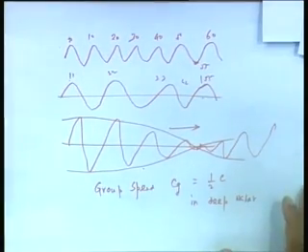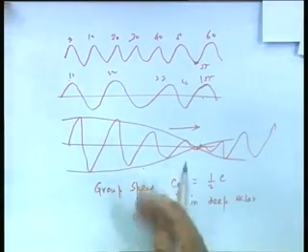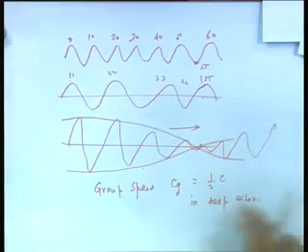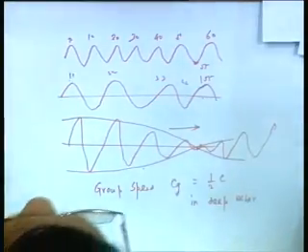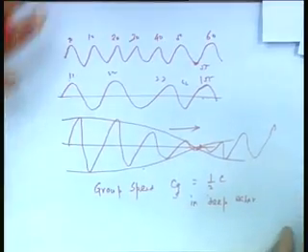In the other extreme, we can show that when kh tends to 0, that is very shallow, Cg tends to C, but that limit is of no interest to us. As I said, for this course on sea keeping, we are mostly concerned with deep water cases, not shallow water cases. Now, this is very important, because the energy of a wave always moves with that speed.